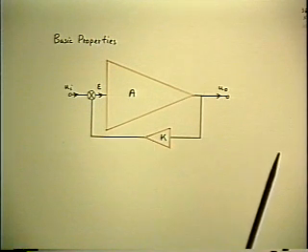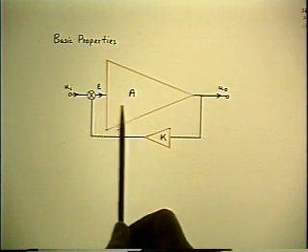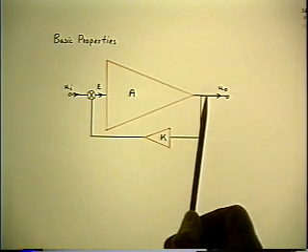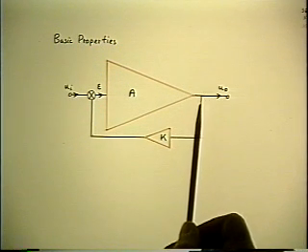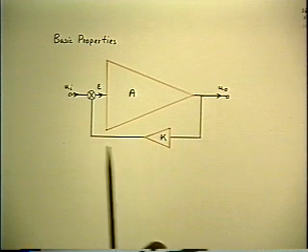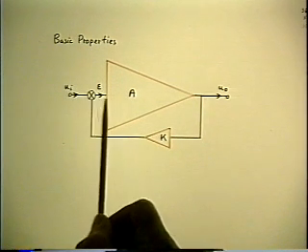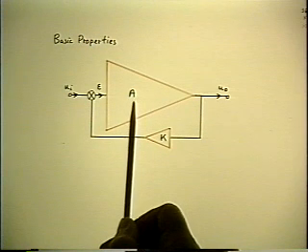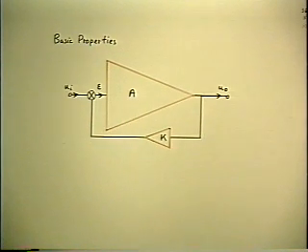If they are, it's easy, which in very many mechanical systems is true. You have a mechanical plant, and you have some sort of sensor which provides negligible loading on the output, and the fed back signal is subtracted from the input in a separate device which doesn't interact with the front end of the plant either. So in that case, the block diagram is realistic.